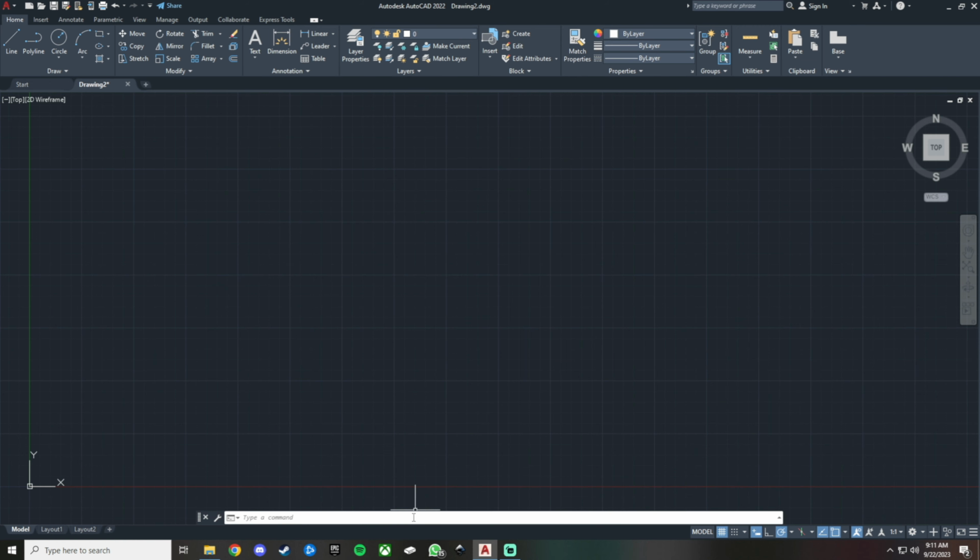The next thing that we have is this command line. A command line is very important. You guys will see that later on while using CAD. The command line comes in pretty handy when you need to use commands. If you want to draw a line, you can type in the command line L and it will start giving you different options. You don't have to just use the line, you can now use length, layer, layout line, but for this one, let's go line.